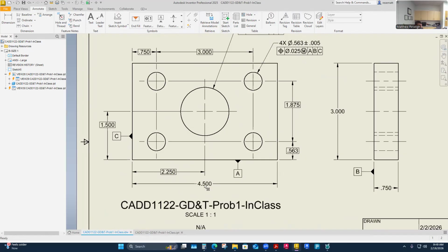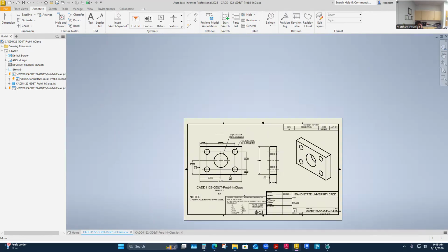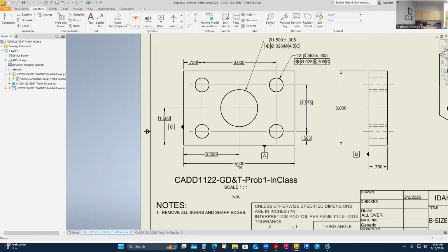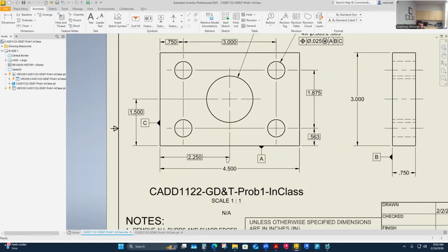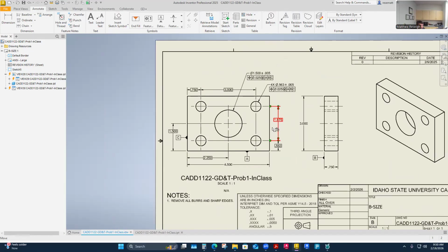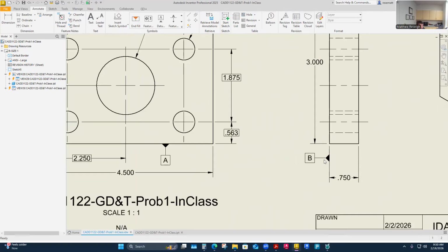Anything that's not a basic dimension, the tolerances apply below. What that would ask in my mind is, how does that impact the datum? I'm like, yeah, good question. It would be some studying there. Do I need to control overall part size from a datum? Maybe, and it's not in this part. So all I want to do is make sure I don't have anything that's kind of weird. Maybe I'll space these off.